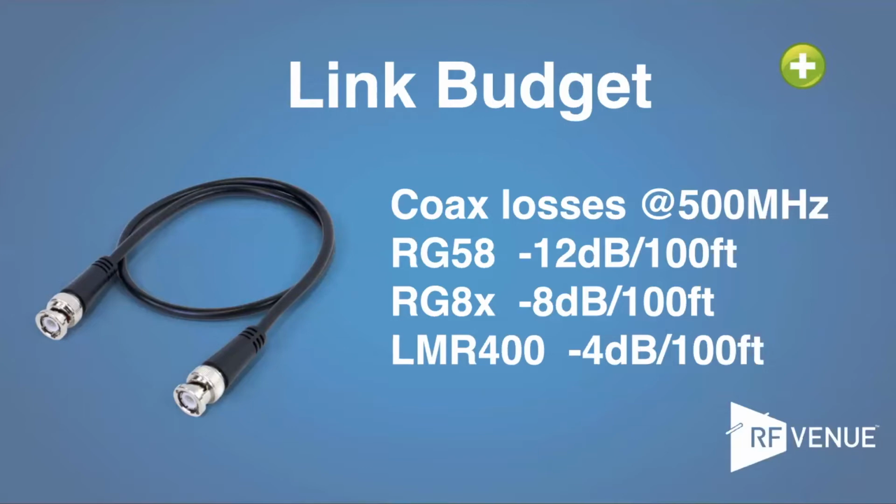But pay very close attention to the frequency that you're looking at, because this wire loses a lot more in high frequencies and a lot less in low frequencies. So don't make the mistake when you go to that spec sheet and see that it's written for 200 megahertz. It's going to make your wire look a whole lot better than it's actually going to be in practice when you get there.